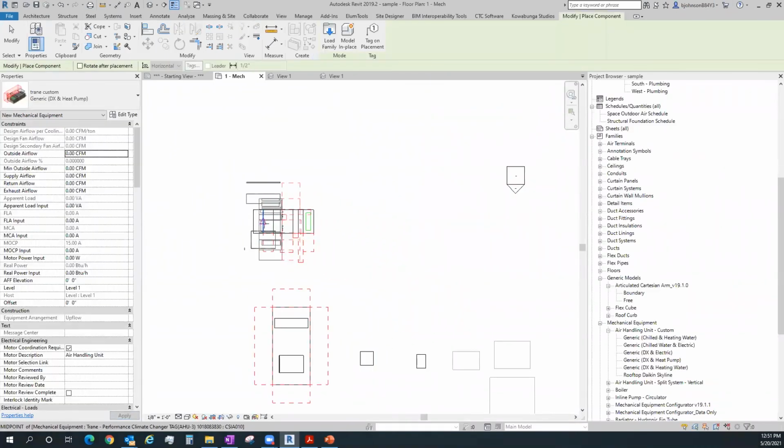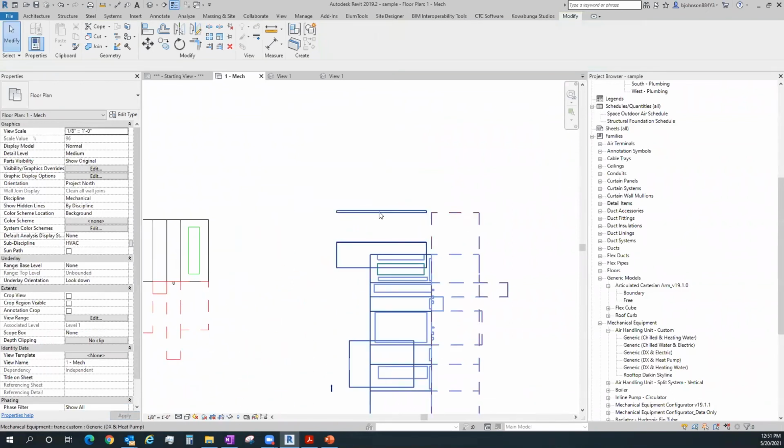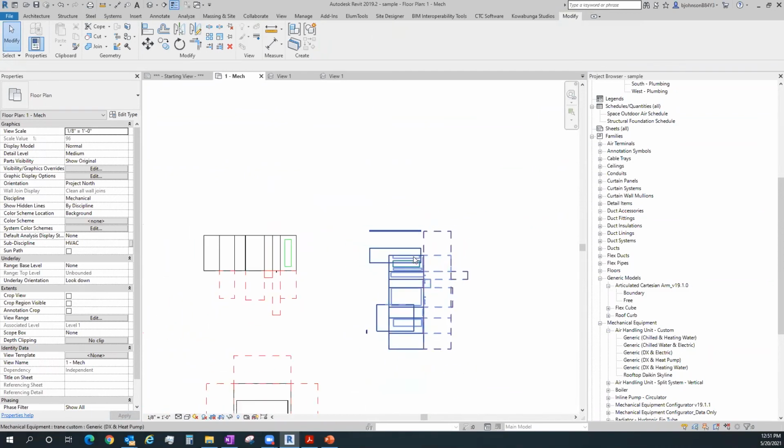So you can see it looks like that one right there, right? I've still got a couple things I need to fix on it, which are my extrusions, the size of my extrusions and the placement of my extrusions. I need to match them to that air handler there. But the 3D component, the big box there, isn't there anymore.